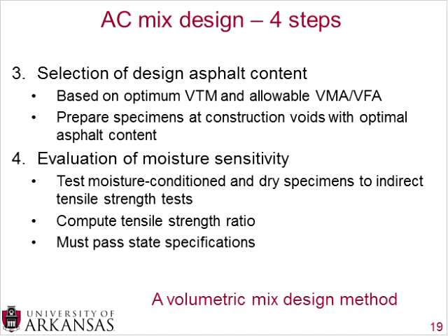And then finally, they do have a moisture sensitivity test at the end of the Superpave design. And you test moisture condition samples, essentially samples that have sat in warm water, and dry specimens, and you test these in an indirect tensile strength test. And you can compute the tensile strength ratio, which is the conditioned samples, so the moisture conditioned samples, their strength, divided by the dry specimens, or the unconditioned samples. And there are usually state specifications for that as well.